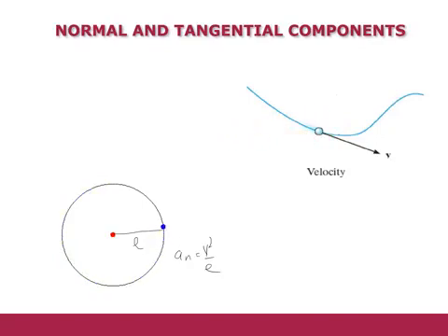Basically, when this type of curve is given to you, we can divide this curve into little segments, like over here, and each segment on this curve will represent the arc of a circle. Suppose this is the arc, then it will cover this whole circle, which has the radius of curvature over here.